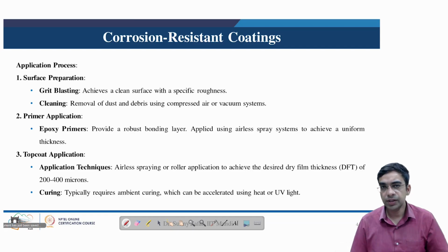which is generally done in ambient condition, or sometimes we may use external heat sources or ultraviolet light to accelerate the curing of this epoxy, because it is a thermoset and creation of the thermoset leads to development of cross-link bonds which are done by applying heat.